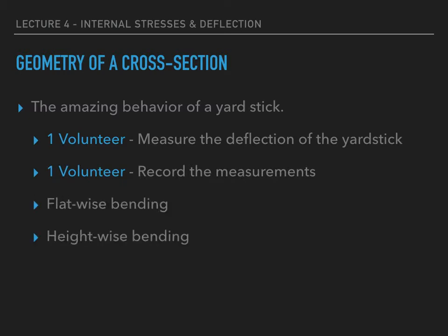So if you joined us in class, hopefully you did. If you didn't, catch up with a fellow classmate, student. We measured the deflection of a yardstick, the flat-wise bending and the height-wise bending to see what the difference was. I think it's pretty remarkable, so make sure you check it out.